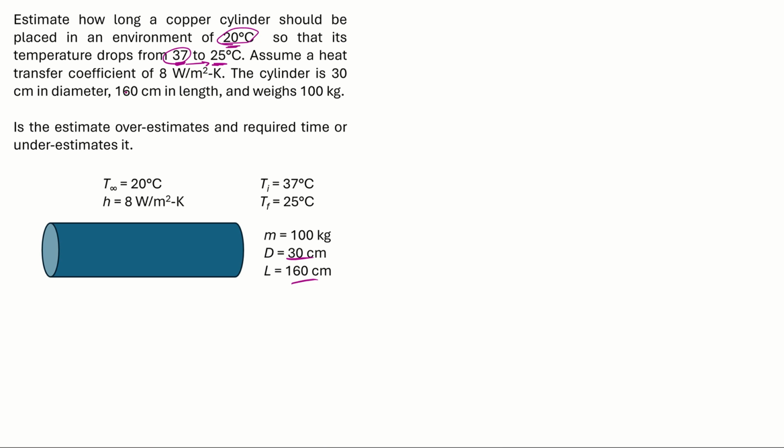We'll assume a heat transfer coefficient of 8 watts per meter squared Kelvin, and we'll assume the lumped capacitance method. It is not exactly a lumped capacitance situation, but I'm going to use it anyway. You'll see why later.